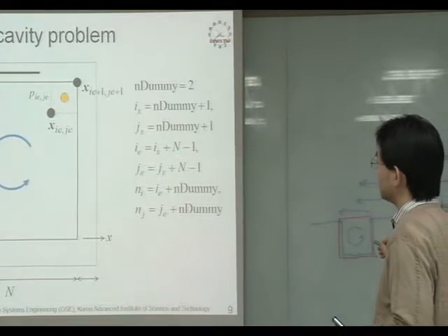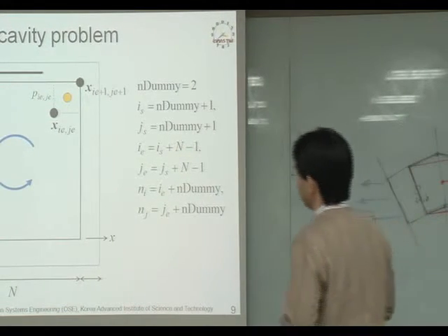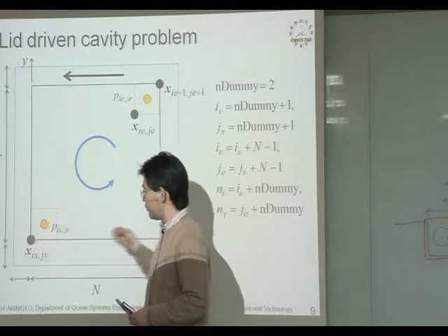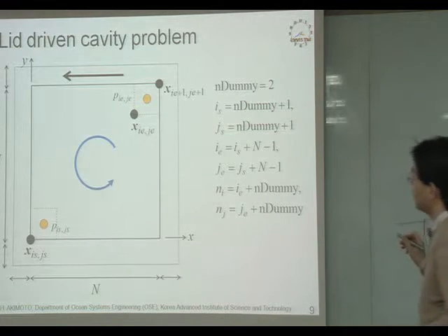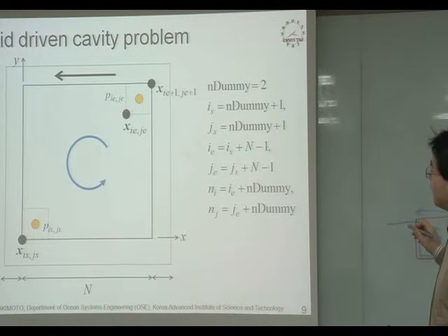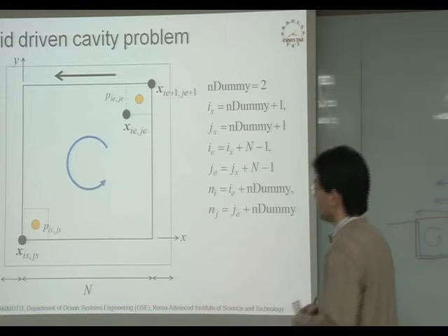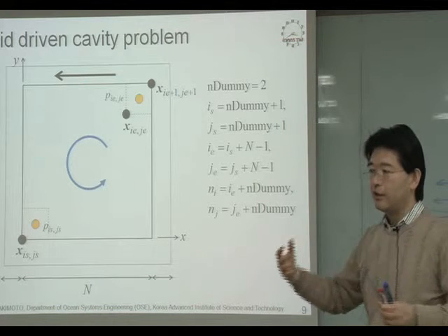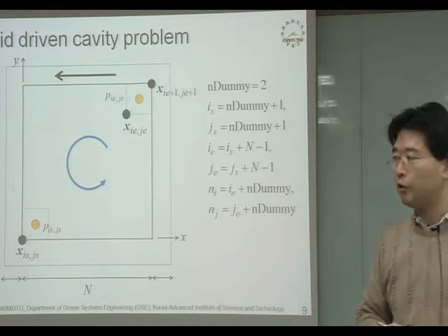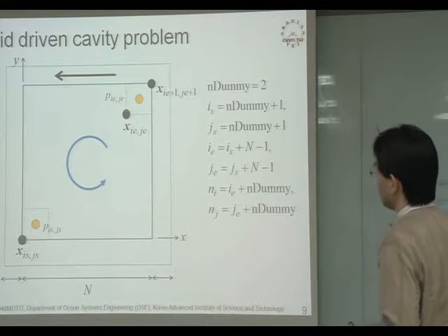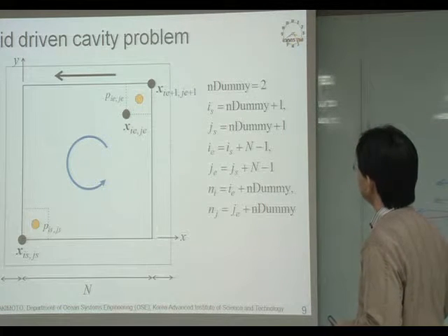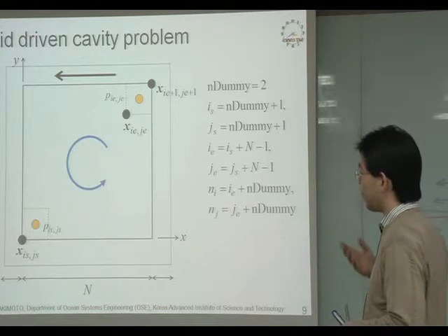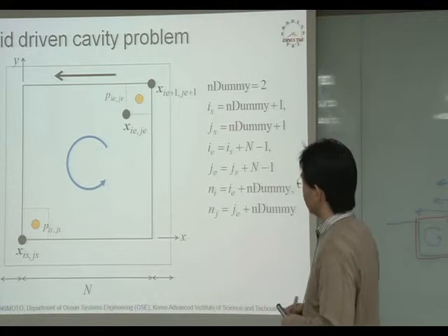And also we have to symbolize the number of control volumes in this direction. So you have to specify capital N as the size of the fluid domain. I guess in the first test case, capital N equal to 2 is enough for debugging and checking.